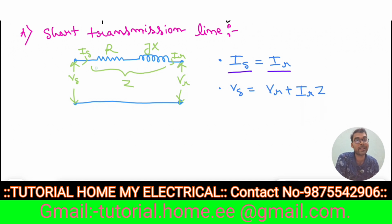Here is the sending end voltage and here is the receiving end voltage. We get the sending end voltage by adding the receiving end voltage to the voltage drop in the line impedance. So Vs equals Vr plus Ir Z.